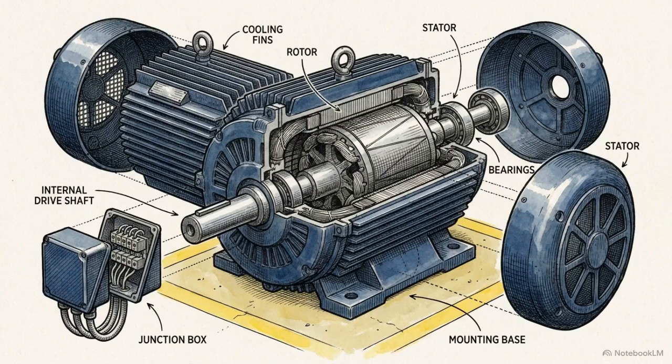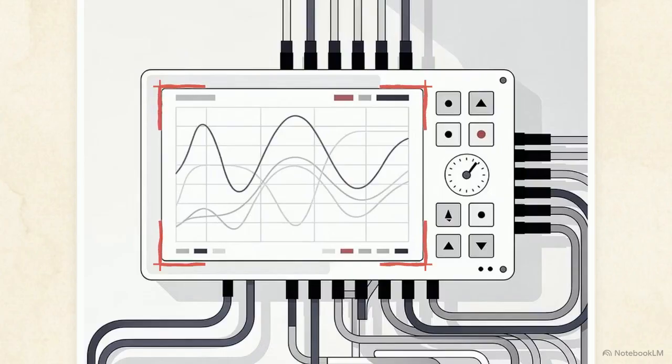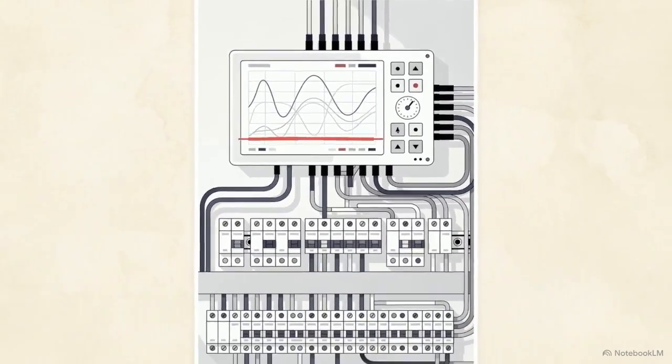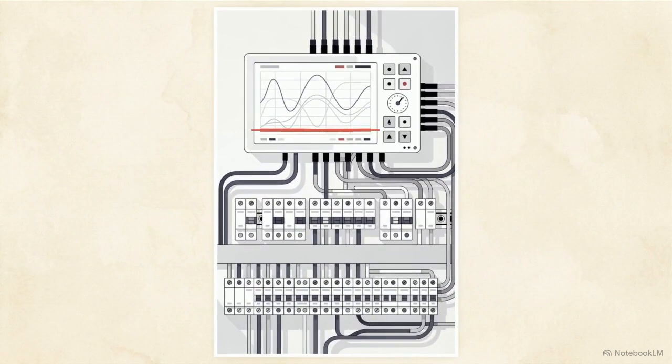On the plant floor, the first major target is typically the largest energy consumer, 3-phase electric motor systems. This analyzer display shows critical electrical supply parameters, capturing active power and issues like total harmonic distortion. These wave fluctuations map directly to equipment performance.